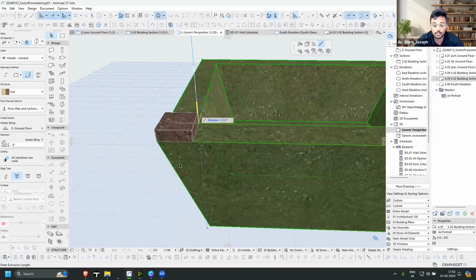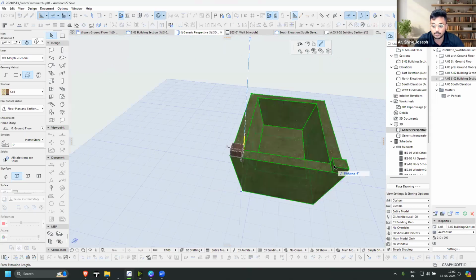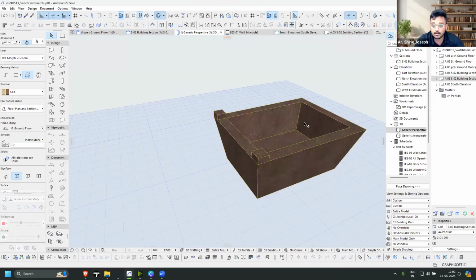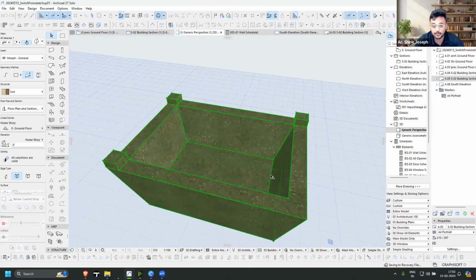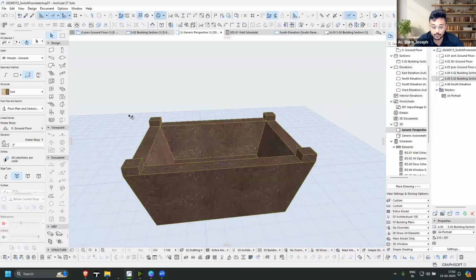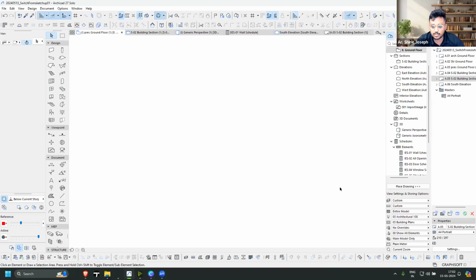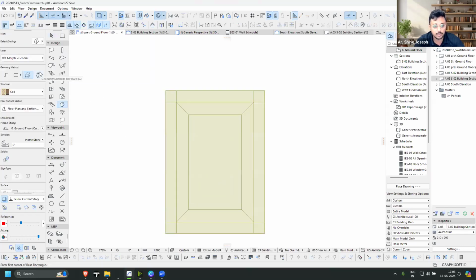So I'm just moving 4 inches from that point. Same thing, I can reflect 4 inch to this as well. And you can always do this kind of modeling within Archicad itself instead of depending on a separate 3D model. The advantage is that this is going to carry a certain amount of information into this. I'll also, in addition to that, use one another option, which is this revolve.